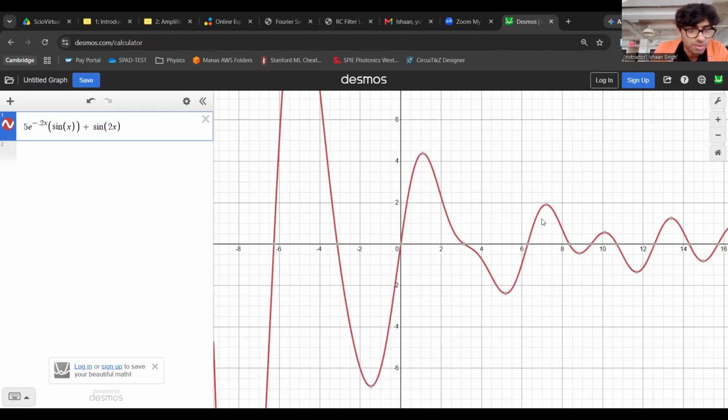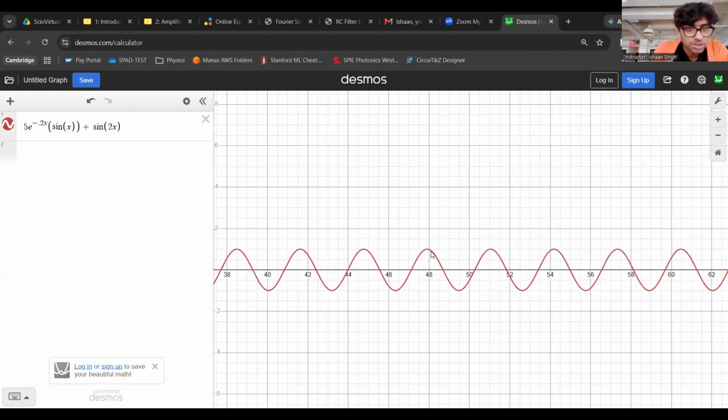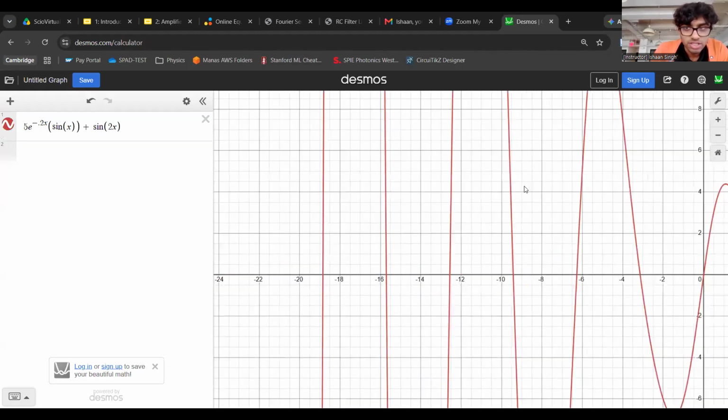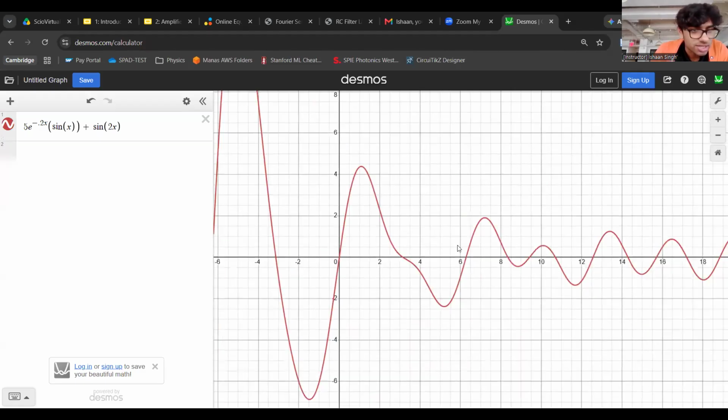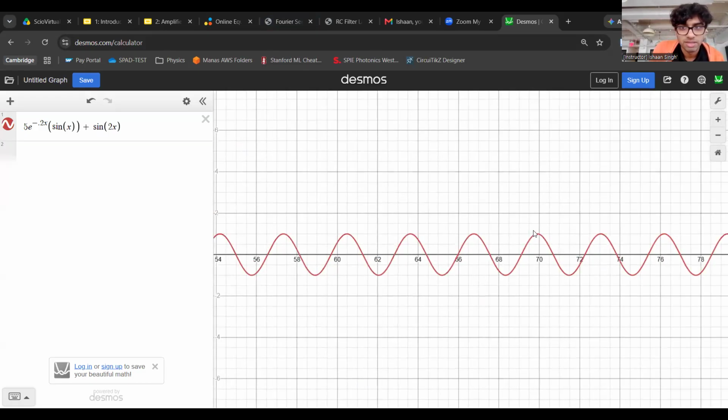This is not a simple shape that we have initially. But then as we progress to a long time outwards, now it starts to look really simple and clean. So this period right here, this is what we call the transient, where things are ugly and it's not exactly clear what's going on. It's still a sum of sine waves, but it's a complicated function. It's not easy to think about. Whereas out here, it becomes simple and it's just a sine wave. So that's transient versus steady state.